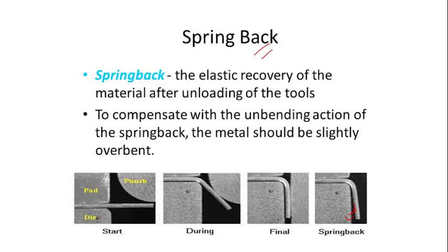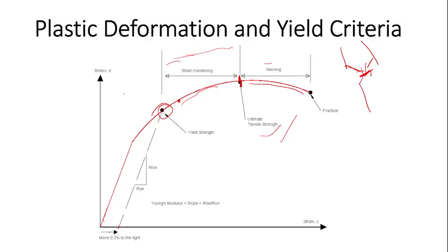What is elastic recovery? They will not ask you what, they will even ask you till here. What is the relationship between stress and strain? It is proportional. So this is your elastic limit, then the proportional limit. After that, plastic deformation will start, right? So you can tell me what will be the strain in this zone, in your elastic limit. Sigma by E, the elasticity, Young's modulus.